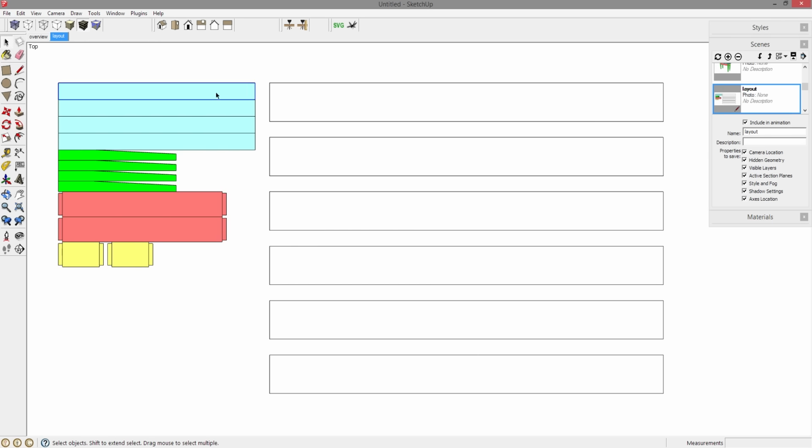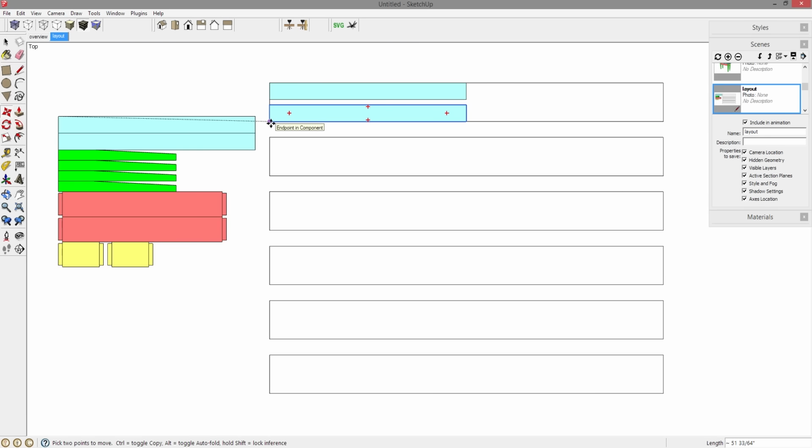Now let's put the pieces into place and the orientation in which they will be cut out. I know that if I'm using a 2x10, typically the center area is the pith, and I'm going to avoid that. So if I put these into place, I'm going to be cutting them like so, pretty much staying on the edges and removing the interior pieces. Let's select all of these. M for move, Control brings up copy. It's easier to copy when you already have them in the appropriate orientation.